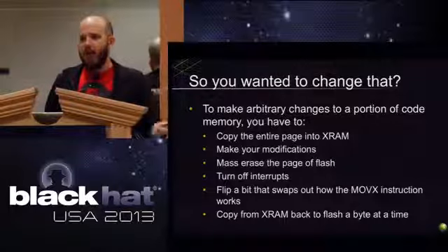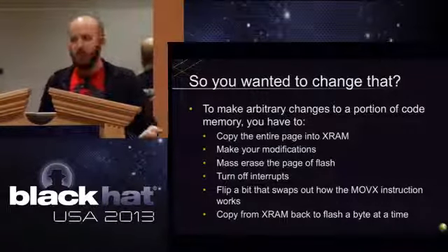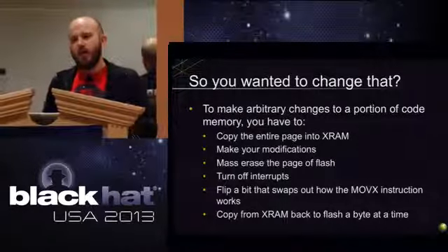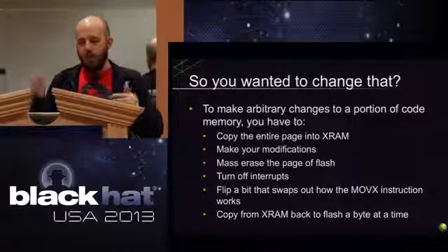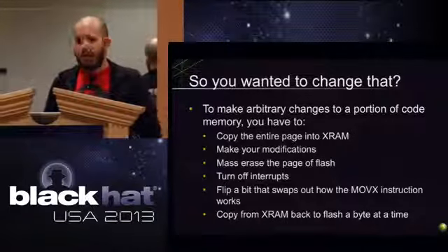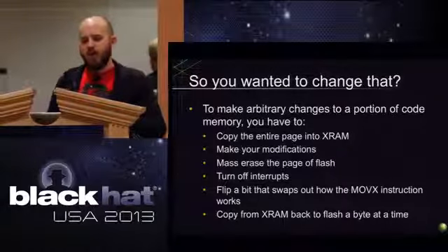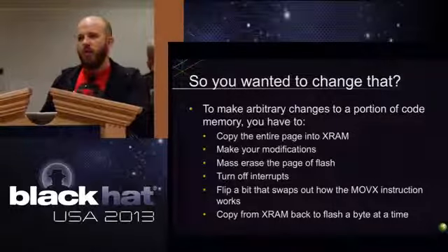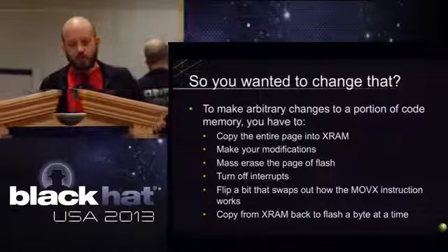But again, that's difficult because it's the same instruction. So if you happen to have that bit on longer than it should be, and some other piece of code runs, then suddenly all of your Flash just got corrupted, right? Because every single function is dealing with movx commands, because that's where it's storing arguments and pulling data out, things like that. And so if you don't get this thing switched off fast enough, then suddenly something else will run, and it thinks that it's fetching and storing data over in RAM, but instead it's actually corrupting your firmware.